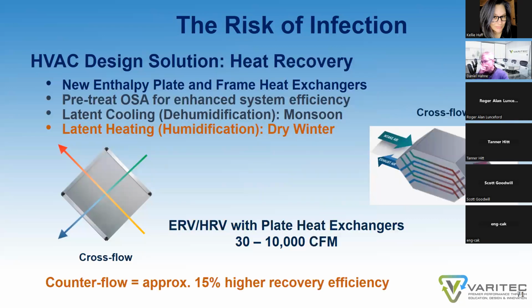So I wanted to bring to your attention, however, a new technology that has come out into the market, which we find very exciting. There is now a plate and frame heat exchanger medium available where we can use energy recovery to drop water vapor that otherwise would be exhausted from a building back into the supply airstream to help reduce the risk of dehumidifying a space due to the exhaust air in a building that is necessary to maintain building pressurization. This technology is currently available in very small sizes of 30 CFM up to 10,000 CFM, and